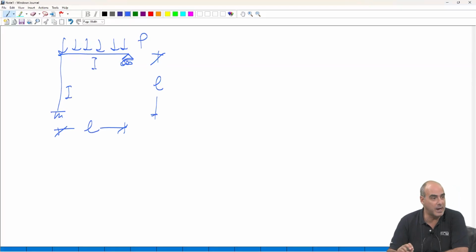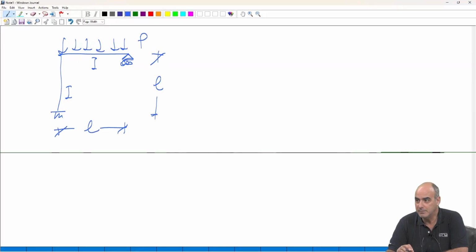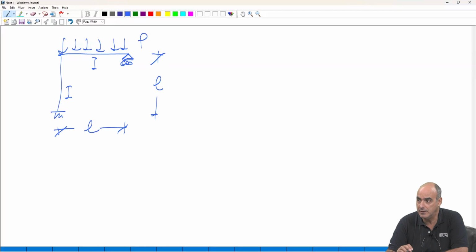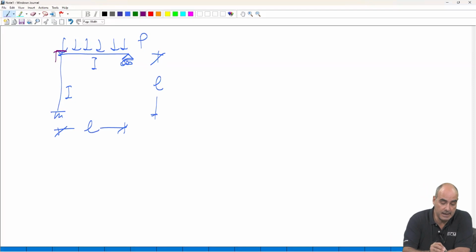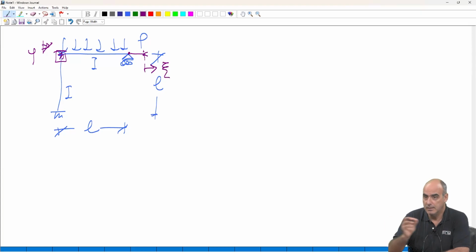let us make it sway. And let us see whether with a sway movement, when I apply the linear theory, it's correct. So here in this case, I have to block this rotation here, but I also have to put a fictitious restraint in that direction.